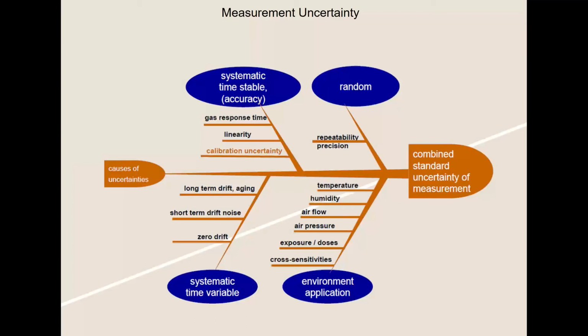Or maybe you're detecting hydrogen. Well, you can't use a video-based flame detector for hydrogen because that is non-visible. So all those things go into account as to what type of detector, what type of transmitter is being used. And if you work closely with the gas detection company, we will be able to help you out in determining that. But we need a list of all the different types of gases and vapors that could be present.